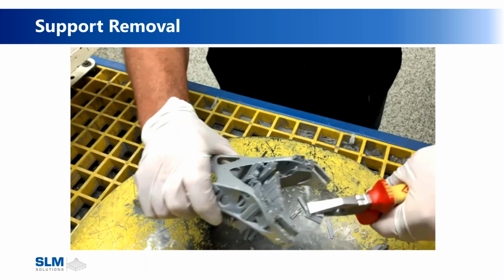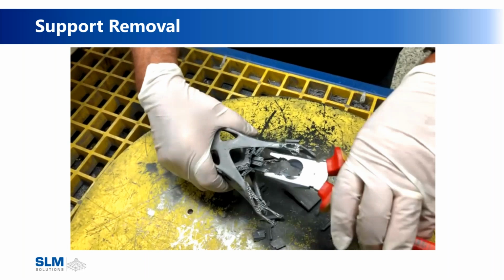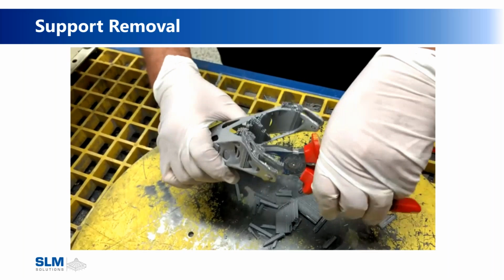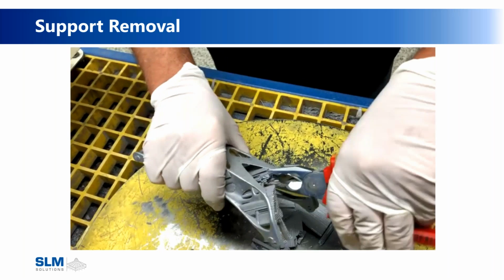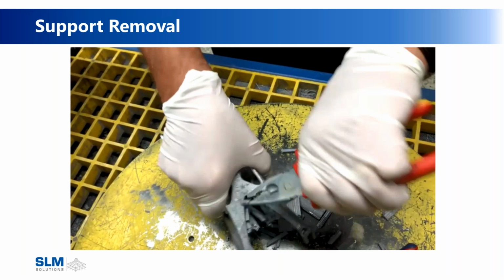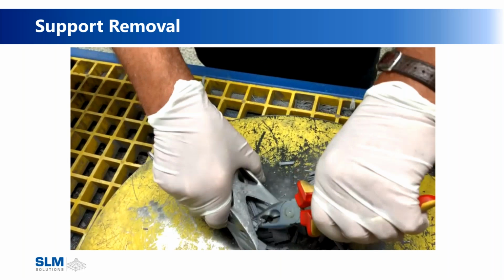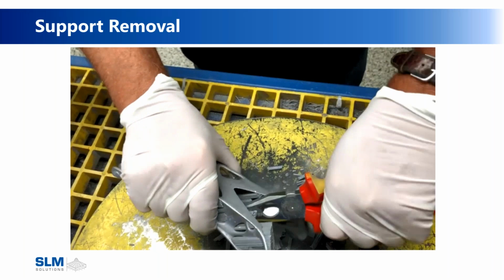Here's a video. So people always ask, how hard is it to remove support? We actually have videos. So this is a part, a smaller version of the bracket we looked at earlier. You can see the support material on there, and we're breaking this off by hand. There's a handful of options, one of them being 5-axis machining, but by and large, supports are removed by hand with hand tools.